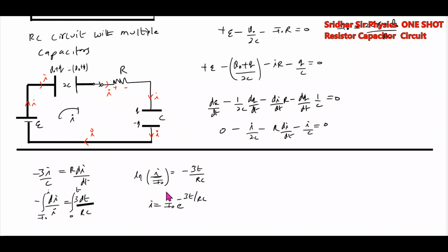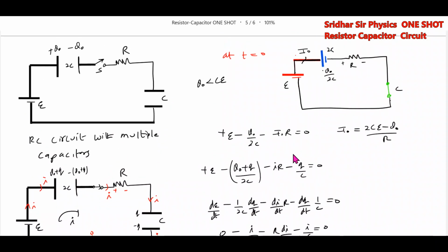Then I equals dQ by dt, and then we'll get the charge. So one charged capacitor, another uncharged capacitor is there, so we have to use this method. Now what is this? A cell, and this is a short circuit. Uncharged capacitor, short circuit; charged capacitor, a cell. There are multiple things that come up, and there's a method you have to apply.